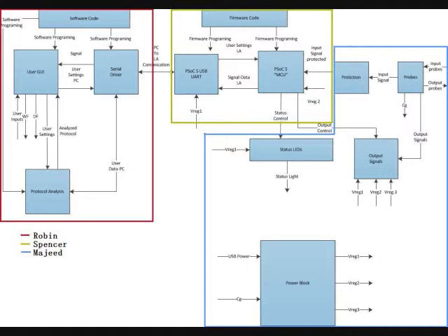In the power plug, we have a 5 V DC voltage coming from the USB, and it will be regulated into 1.8, 3.3, and 5 V DC voltage. In the output control block, we will be controlling our output voltage by the MCU. In the LED status block, we will turn our LEDs on and off by the MCU, and it will show different light colors for reading, waiting, and power. The probe block will show the physical connection.